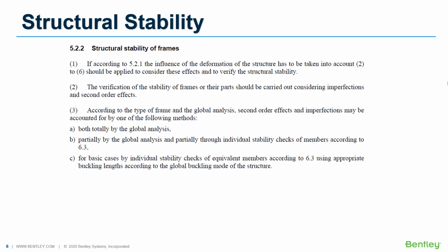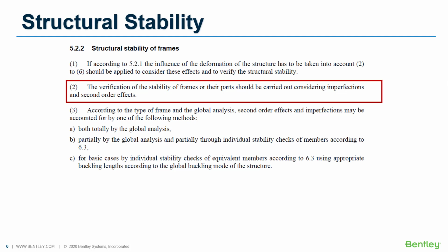Now the analysis method is fixed and we have to ensure the stability of the frames. This should be ensured considering both the second order effects and also the imperfection. Eurocode suggests different approaches depending on the type of frame.